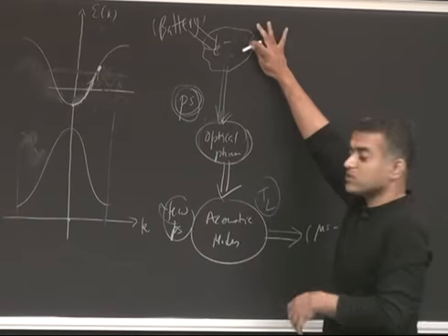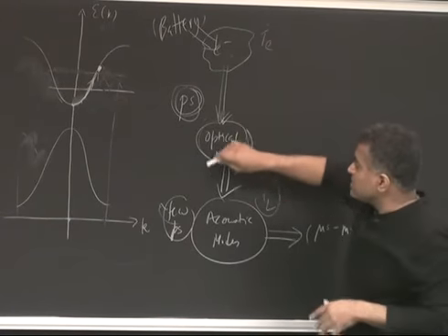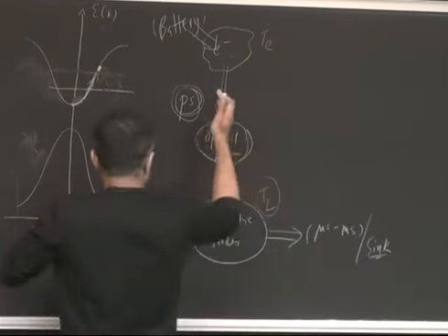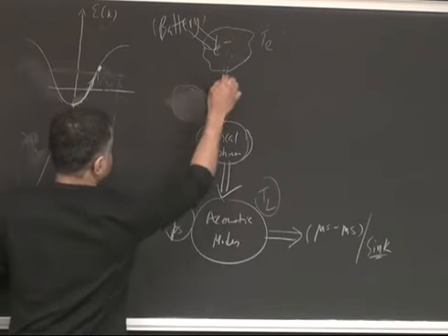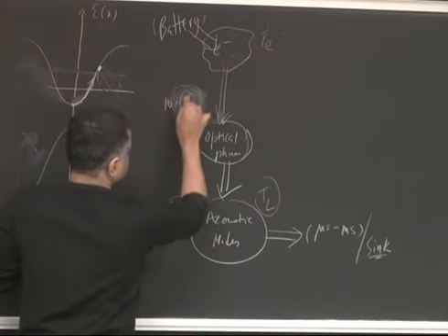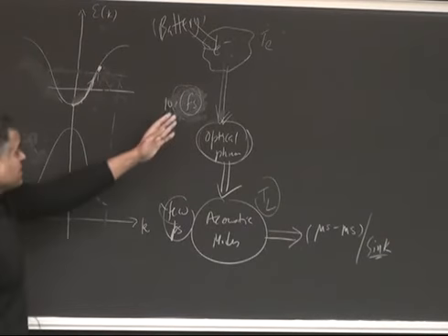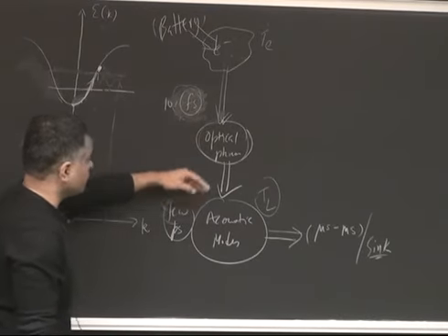So for the electron, that we call a hot electron. Sometimes what happens is, in gallium nitride and some of this aluminum nitride, this electron to optical phonon time can be tens of femtoseconds. It's much faster. The optical phonon coupling is very strong in a highly polar material. In that case, this is a few femtoseconds, but this is still a few picoseconds.